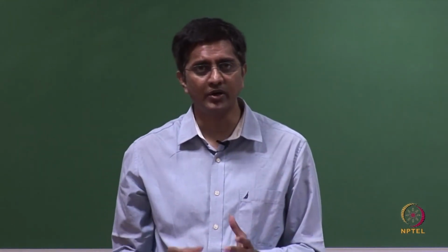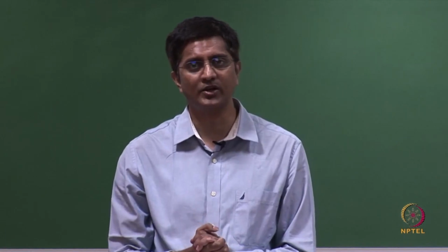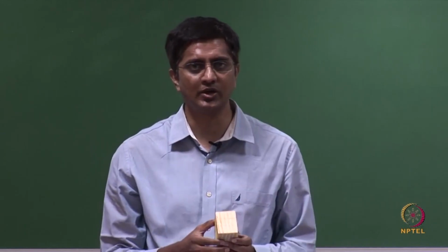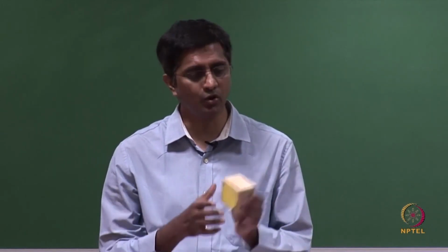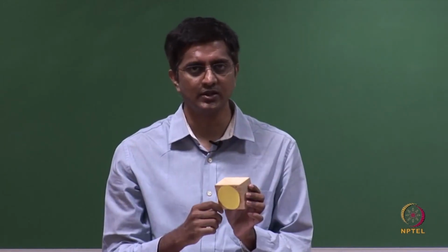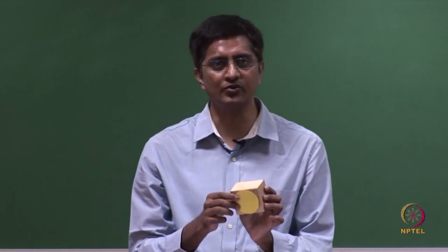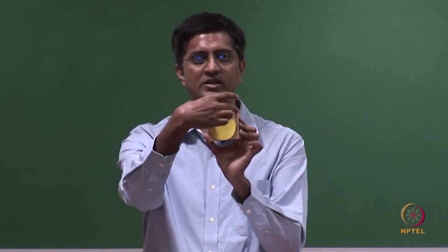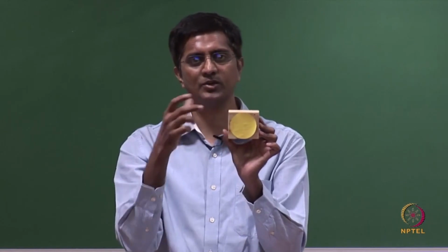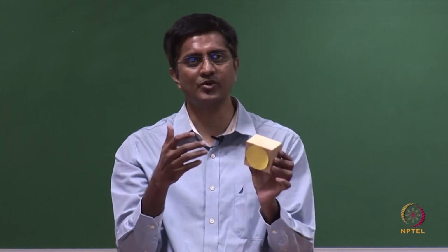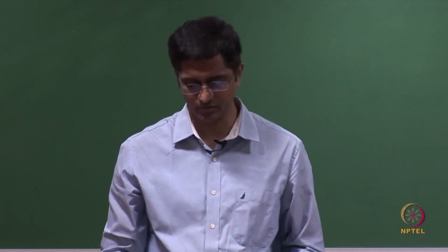But an important aspect, or the limitation, of this multi-view projection is that probably one single view is not sufficient to completely describe this object. Though you are able to describe one face of it very accurately and with true lengths, based on one single view you do not know what is the depth of it. Maybe the depth is just the same as the height and the width. In that case it becomes a cube, but let us say if it is half, it is a cuboid, and that information is not available in this single view.